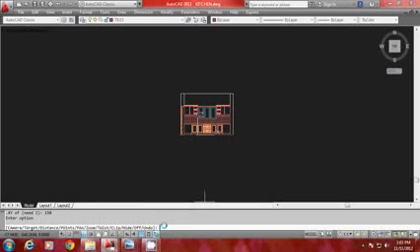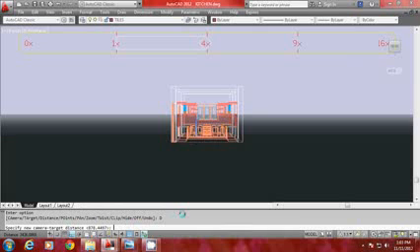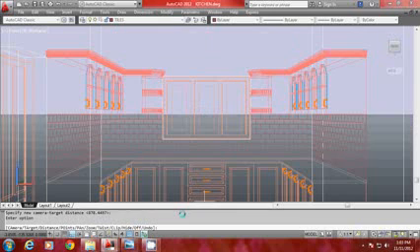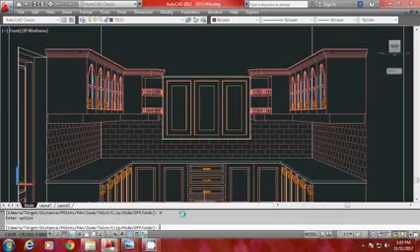So if you want to get back to perspective, just go to the distance option, type D here. Now it will show you the current distance separating the target and the camera. You can either just give an enter to select this distance, or you can give a different value if you want to vary the distance. So I'll just give an enter. Then I give hide. Now you have got a perspective view here.